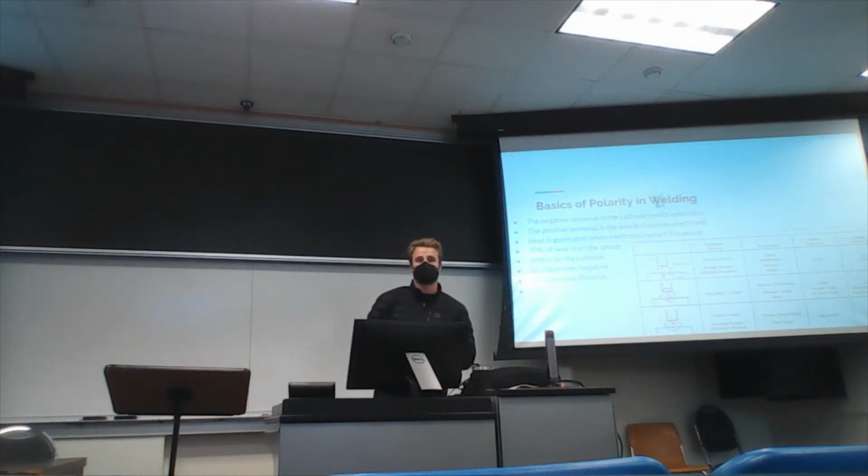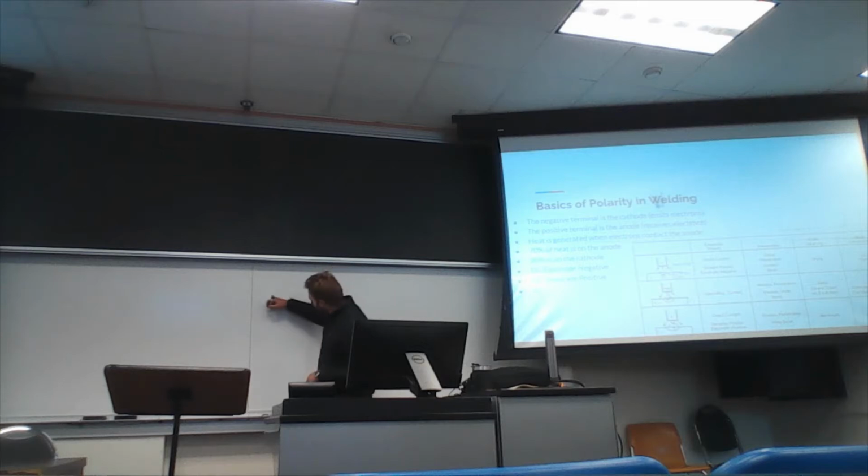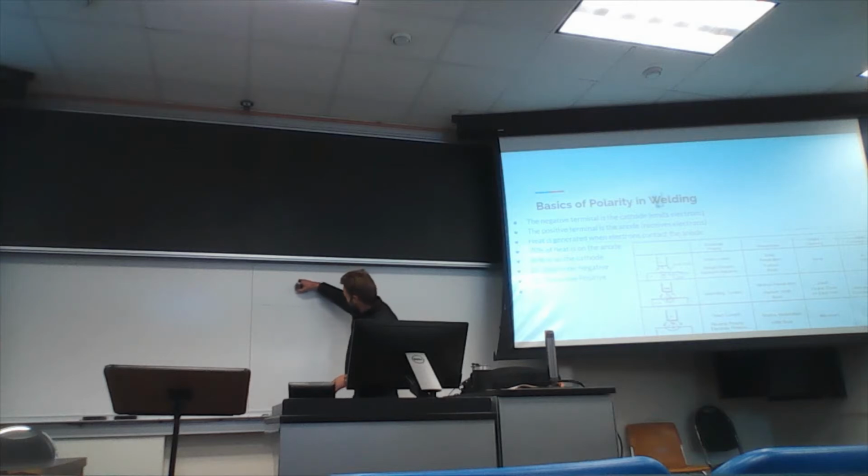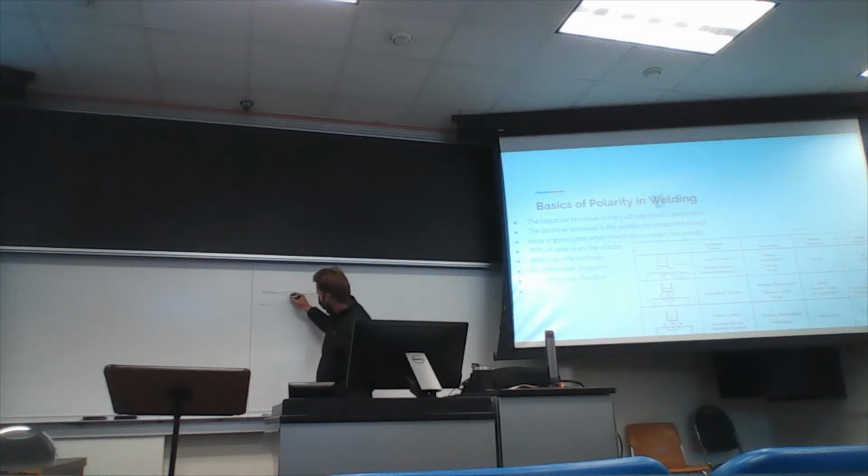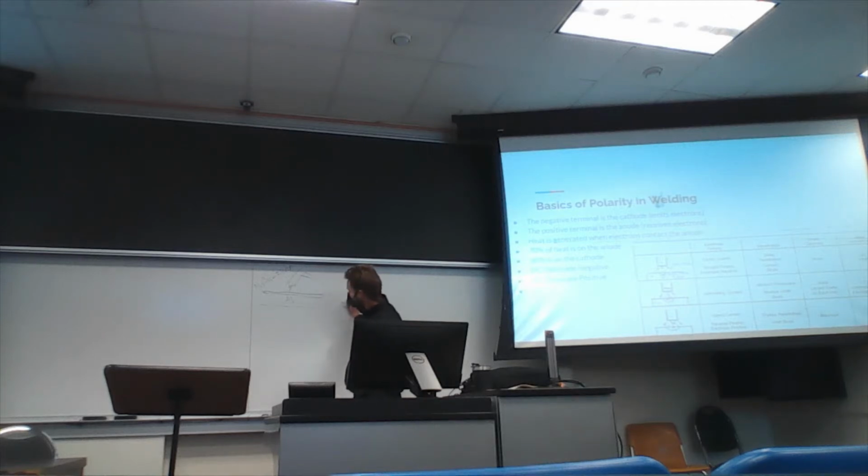So this is just a little bit more in depth of what we did in class, but when you weld aluminum, due to the oxide layer, which is Al2O3, which melts at 3700 F, and you got your welding torch, which is normally set up in DC electronegative for TIG welding.